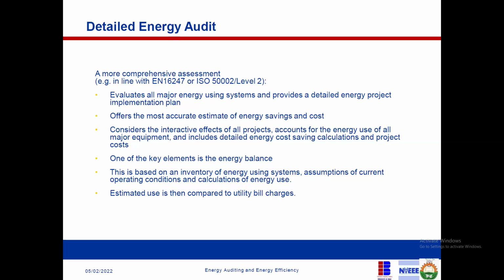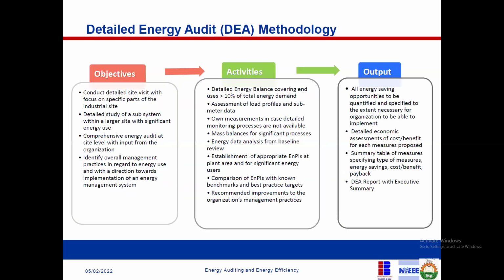However, the detailed energy audit is a little bit different. In a detailed energy audit, we have to conduct the site visit just like we did in walkthrough. But this time, we'll do a comprehensive energy audit at site level with input from the organization. So we'll do comprehensive energy auditing by doing load analysis, calculating the load, going through all the equipment, taking readings, taking note of their nameplates, checking what they are consuming.